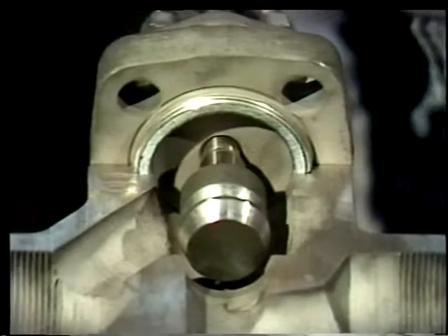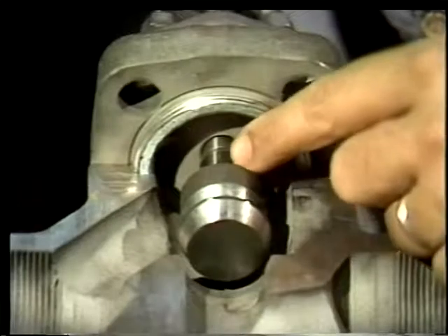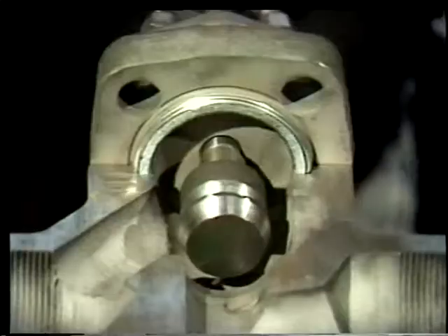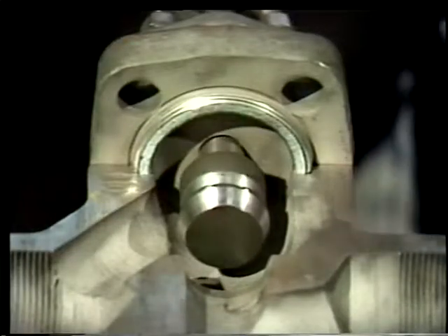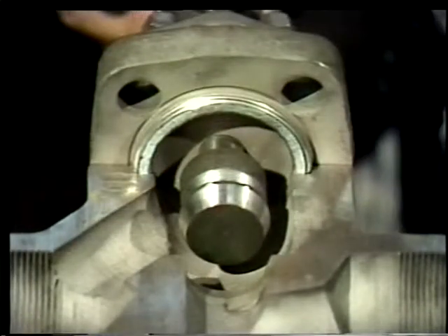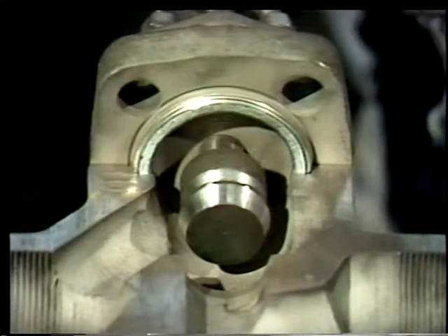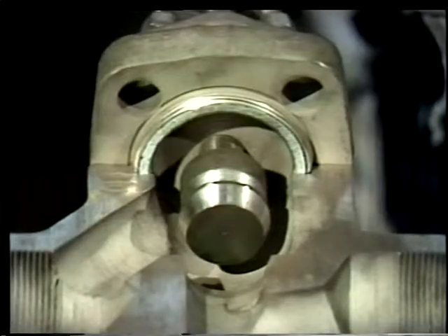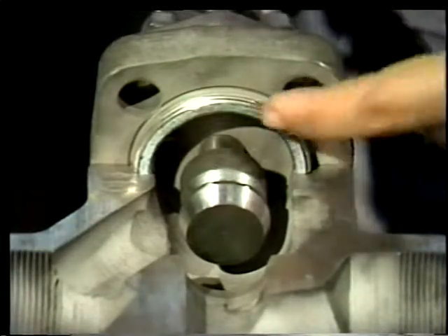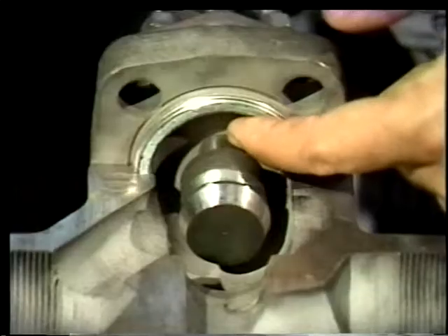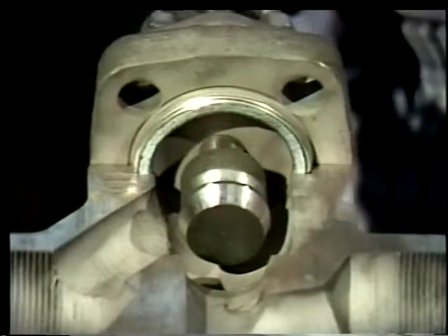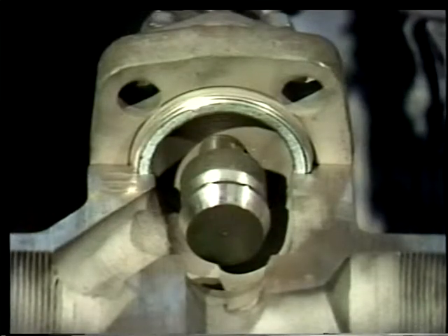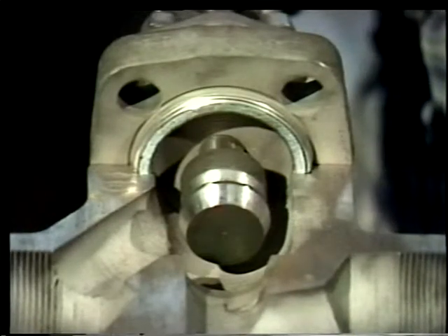Many globe valves are made with a seating area above the disc, like this one. It's called a back seat. When the valve is fully open, the disc will seat against the top of the bonnet. This keeps system pressure off the packing. Manufacturers advertise that packing adjustments or repairs can be made while the system is pressurized with the valve on its back seat. However, for personnel safety, we recommend that you do not perform valve maintenance while it is under pressure, even if on the back seat.